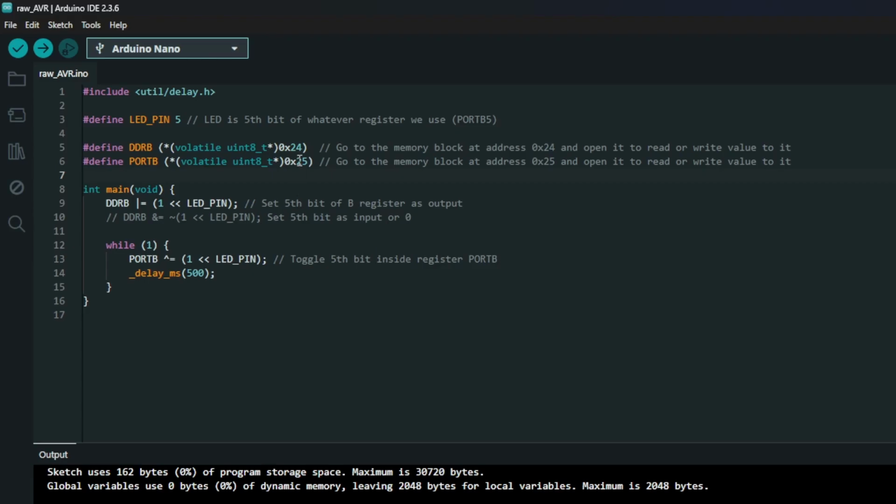So essentially, first thing, volatile. This keyword in the AVR world, I think AVR world, maybe in other microcontrollers, just tells our compiler to not ignore this line here, because our compiler will ignore this line in the optimization process, and our compiler is very smart, so it can optimize our program even more and remove things that we never used in code.